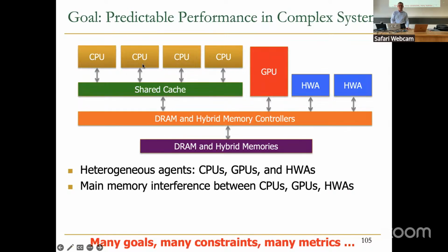So you have many different types of accelerators. This paper doesn't do justice, actually, but it's kind of my cartoonish picture. Let's say you have general purpose cores. They could be small or big. You have GPUs, small or big. You have hardware accelerators, different types: video encoding, decoding, for example, audio. More and more machine learning accelerators that are more specialized for the task. It could be a vision accelerator, for example, especially in an SoC for different use cases. You can have a lot of these different compute units.